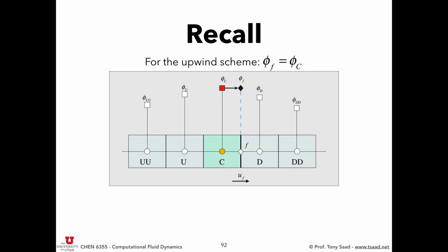And with this nomenclature, remember, C is always the upwind value, D is the downwind value, U is the far upwind, and so on. So if the velocities were reversed, this cell would become C, this cell would become U, this cell would become D. Okay, so this is a bulletproof nomenclature. It just works when we're constructing these schemes. But once you go ahead and do an implementation, you can switch to i plus 1, i minus 1 indexing.